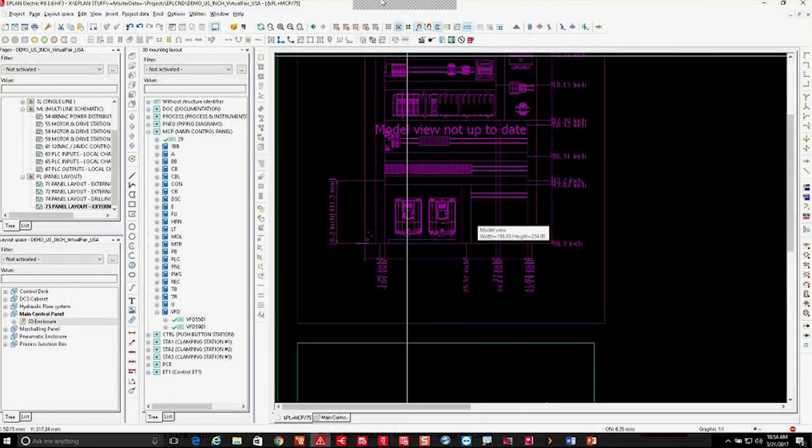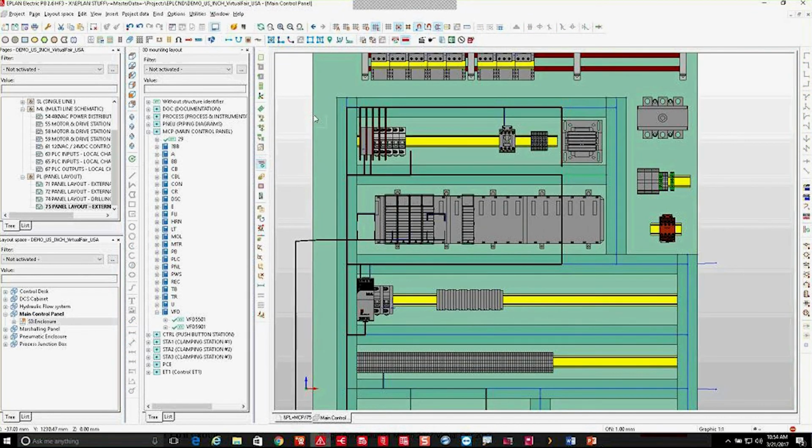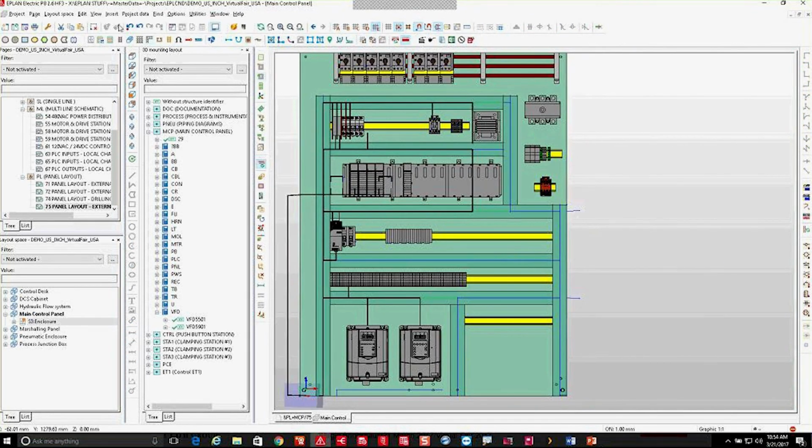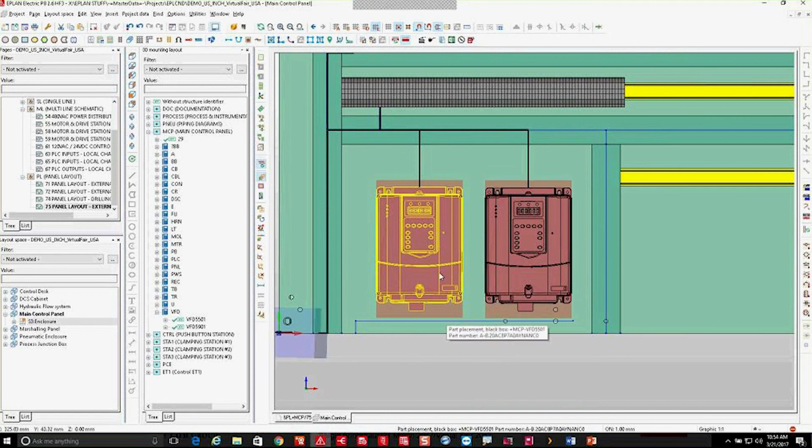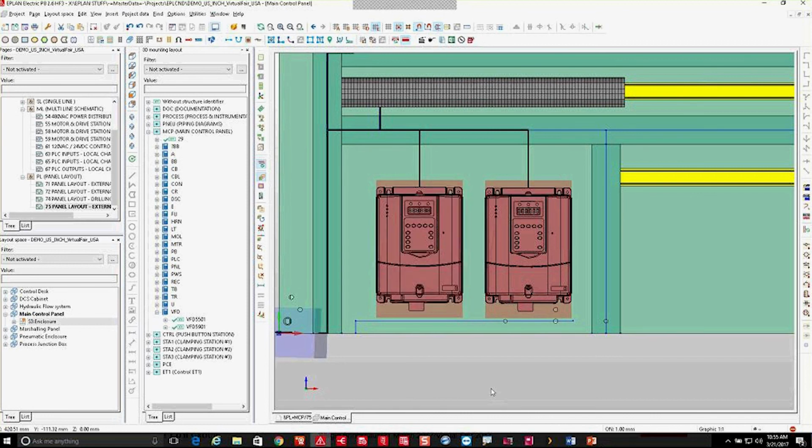There were questions about collision checks. Of course, as we stated, we have the different views available for mounting clearance that we can state. For the collision check, we do have a collision check function that, once it's enabled, when you're placing components down that might have some heat dissipated zones, as I demonstrated earlier with the VFD, will not permit you to place that component inside that area. So huge, huge benefit. A lot of errors are going to be corrected within this view.